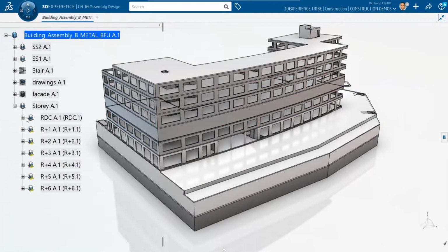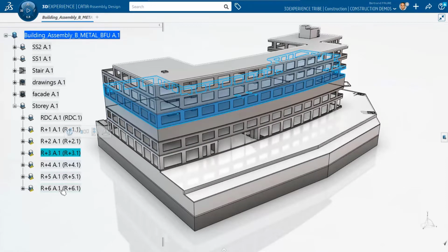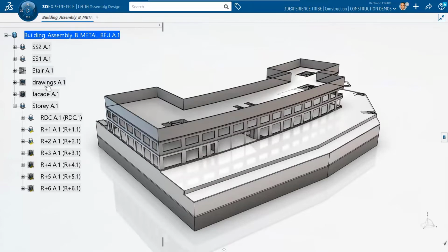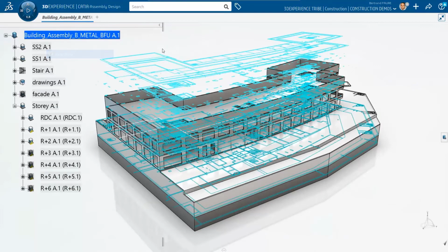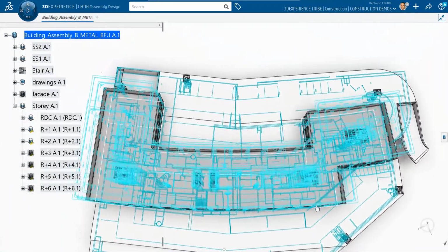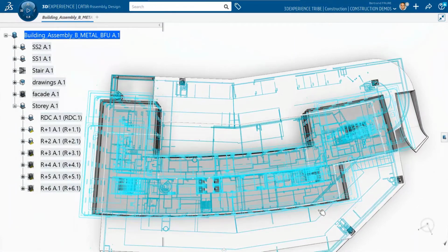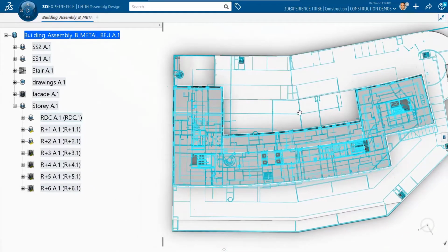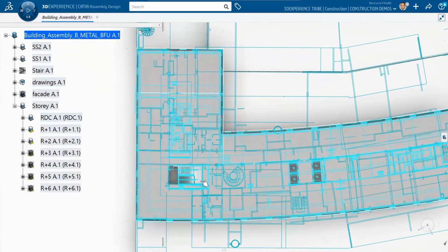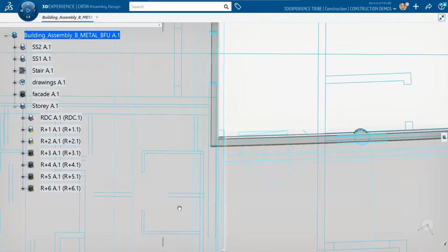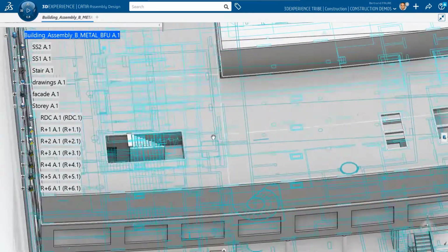Of course, the building is finished already, but I'm showing you how I would continue the modeling from the second level. What you see in blue is the different drawings imported from the architect office and cleaned up in DraftSight. Why is it so important that the drawings are reworked? Because they are going to be displayed in my 3D environment all together. For example, here all floor plans, at each level.